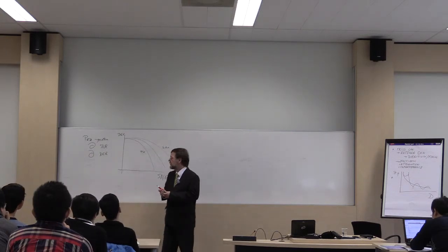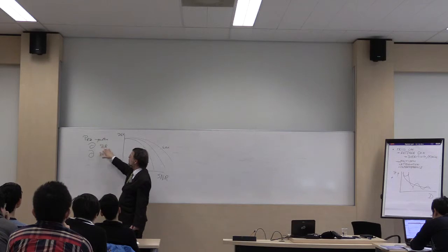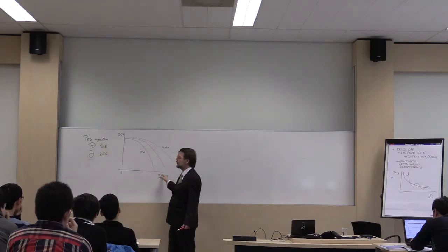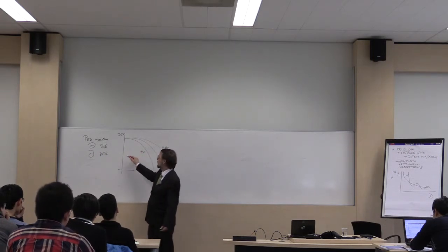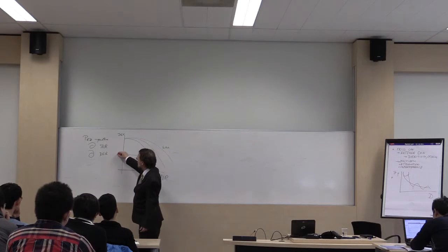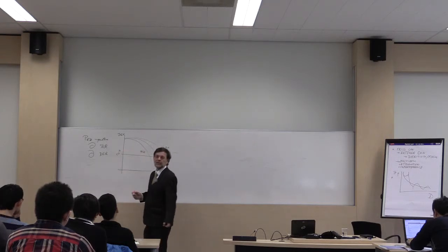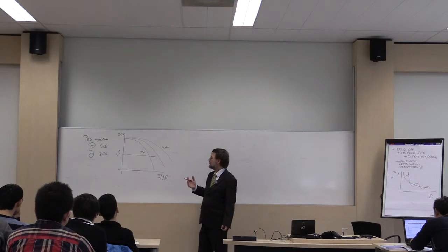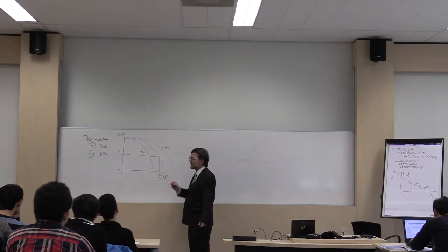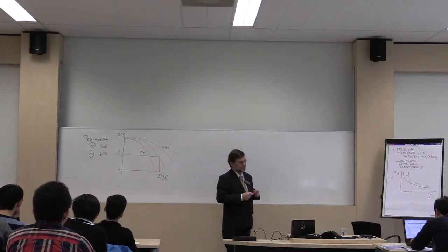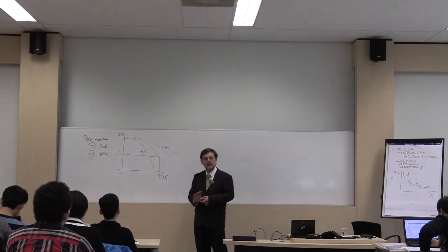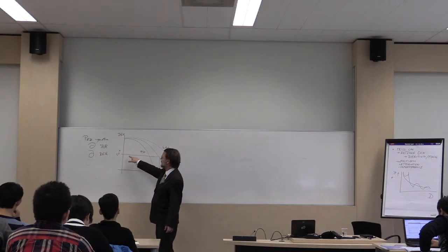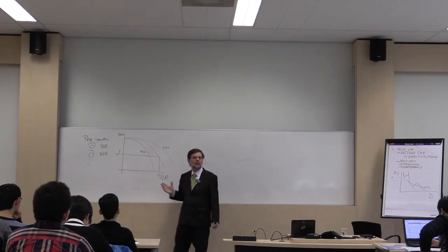And so in the same way that for analog systems you have a signal-to-noise ratio that you define, through this curve you can relate that signal-to-noise ratio directly to the bit error rate that you want to have, let's say a bit error rate of 10 minus 3. So every 999 bits that are correct, you allow one wrong bit. And then you can find the corresponding signal-to-noise ratio if you know the modulation. And that's one of the nice things about digital systems: the error correction allows you to have perfect reception until that point, and then it stops abruptly.